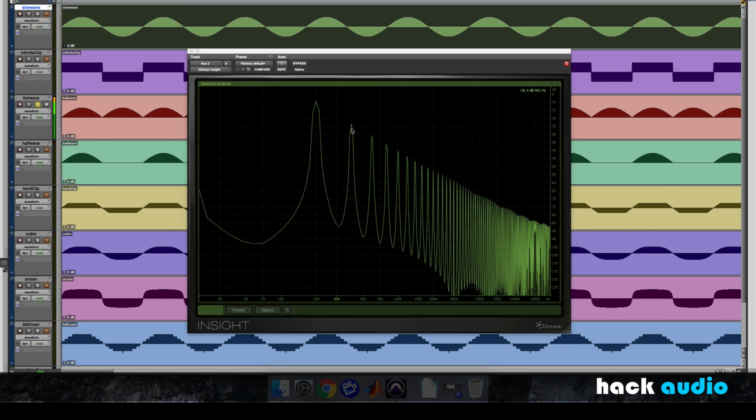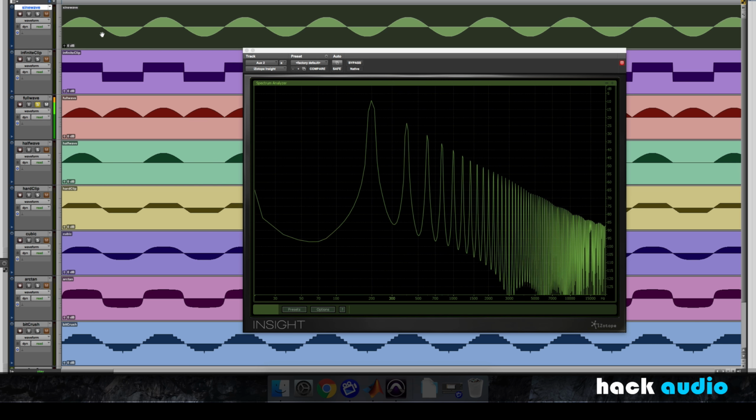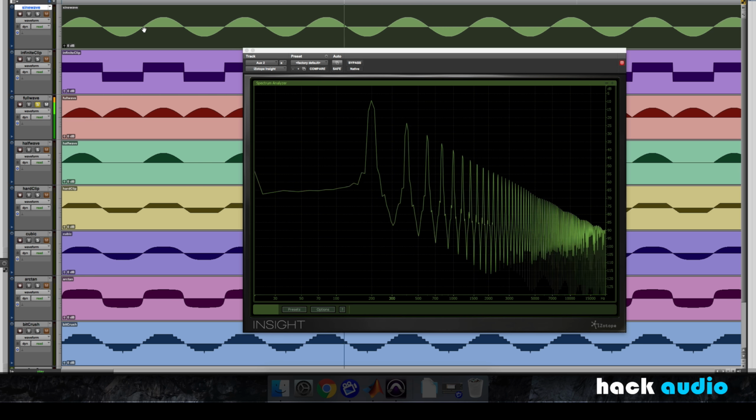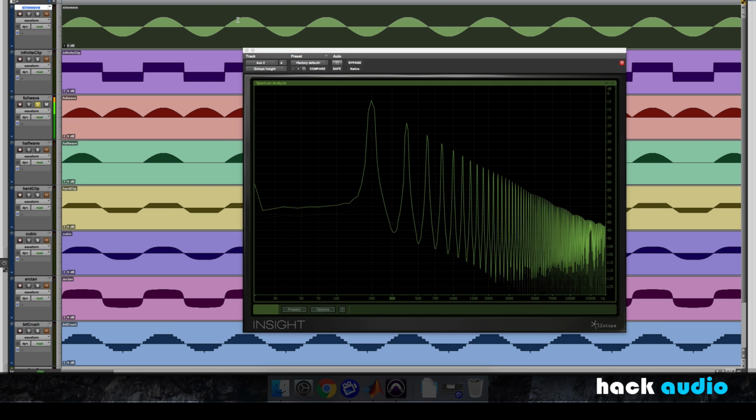200 Hz, 400 Hz, 600 Hz, 800 Hz, and so on. In fact, we don't even have our fundamental at 100 Hz in this case. Looking closer here at our waveform, let's consider how often this sine wave repeats, its period. It's going to go through a full cycle where it goes positive and negative and then starts over this same pattern again. Now let's look at the full wave rectification.